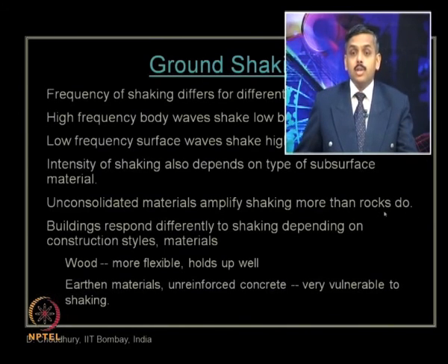So, rock generally does not amplify the input ground or base-level ground shaking much, but unconsolidated material or soft soil will amplify or increase the seismic acceleration when the waves pass through it. That is why we have to be very careful about soft or unconsolidated material existing below our site of concern, where we are going to construct any new structure.